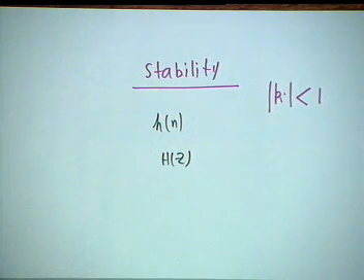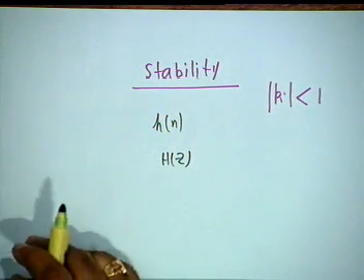Factorizing the denominator itself requires another subroutine, a pole or root finding program, and root finding programs have their own disadvantages. For example, numerical inaccuracy. Any root you cannot find up to an infinite number of decimals. You truncate somewhere, and then you go and happily design the filter. Oh, my filter is stable, and then the filter starts oscillating, because of quantization errors.